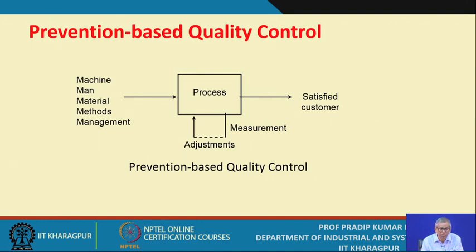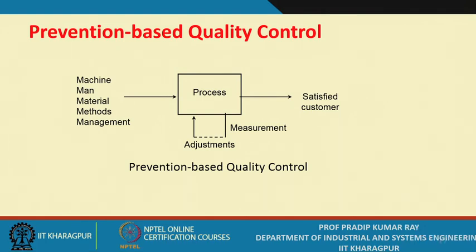And in the process planning component, for any product you produce, the way you create the process plan ultimately determines the quality level. It's a total document where the process plan has the details of all the operations, their settings, the kind of machine tools you use, kinds of jigs and fixtures you use, kinds of setup you do. Is it okay? And ultimately you need to control production related variables also.